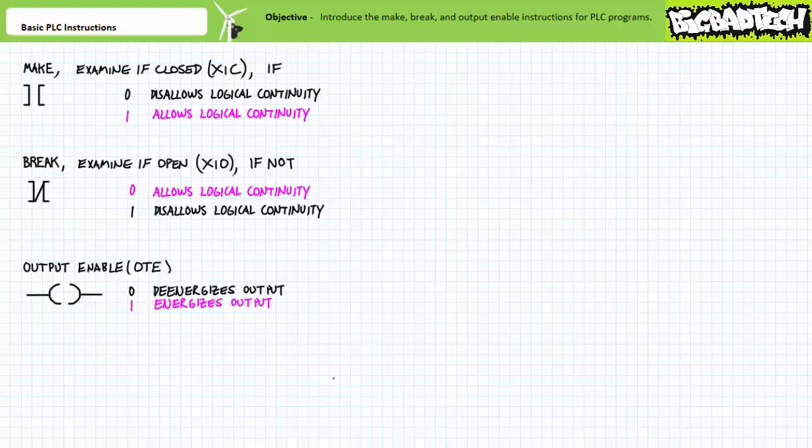Loads hooked to a PLC output include the coils of contactors, the solenoids of fluid power valves, and indicators like LEDs. Normally, a PLC delivers output signals via an electromechanical relay for AC or DC loads, a solid-state transistor exclusively for DC loads, or a triac or back-to-back reverse parallel SCR exclusively for AC loads. Let's assume we're dealing with electromechanical relay outputs since they're the easiest to understand. We'll discuss the peculiarities of the solid-state devices in other lectures. If an assigned output receives a logical 0 via the output enable instruction, the electromechanical relay coil is de-energized and the contact remains in the deactivated open state.